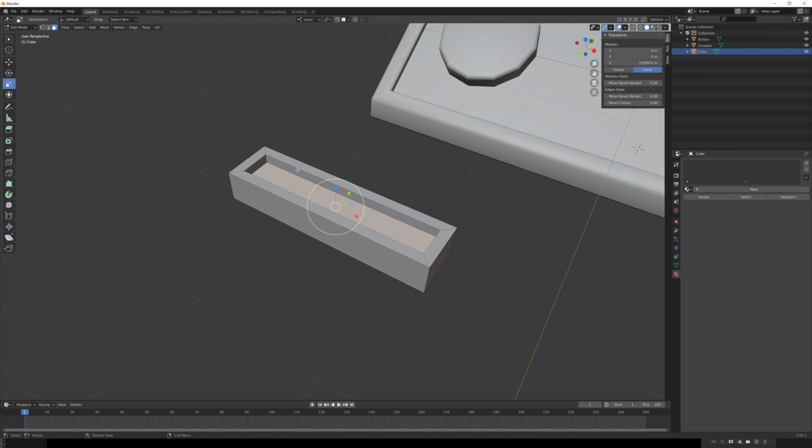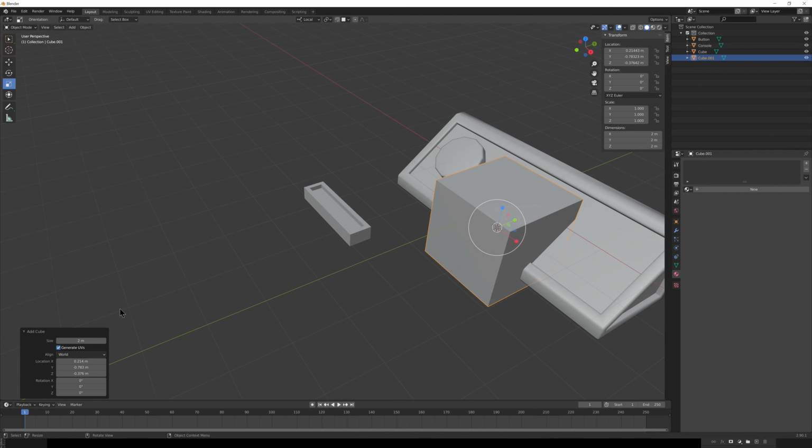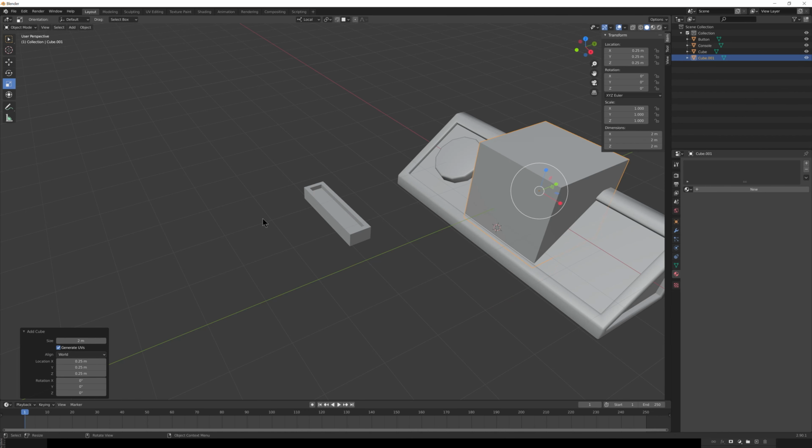So to create the object in the channel, we could use the channel itself to help us, but since we chose easy numbers in this case, we can pretty much do it by just going to Tab to get out of mesh mode, go to Add, Mesh, we'll add another cube in this case, and we know the dimension was 0.25. So I'm just going to select everything, go 0.25 right there. Whoops, that was location. Let's zero that back out for a second. The size, 0.25 right there.